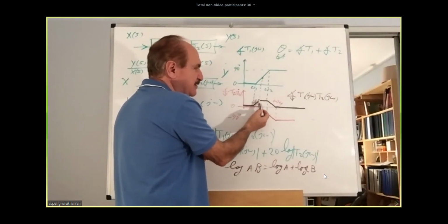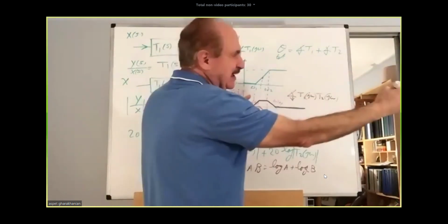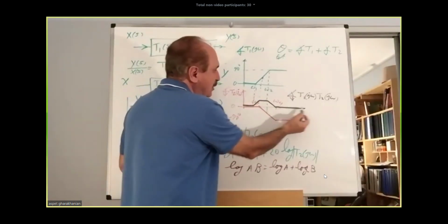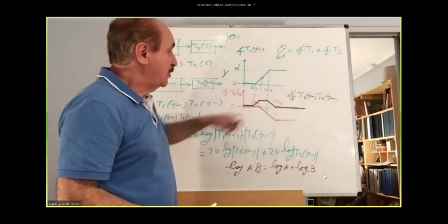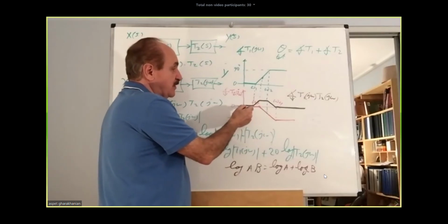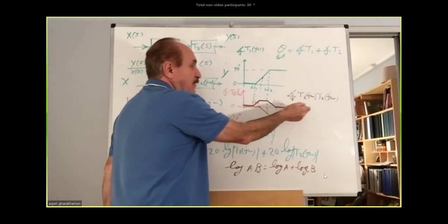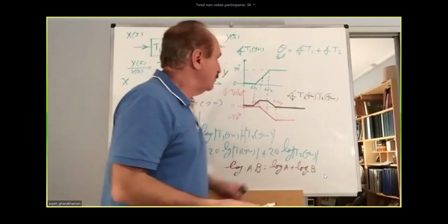It will stay maximally flat, or kind of peak to a maximum, and then it will start going down, and eventually it will become a 0 degrees phase shift. Of course, this combination shows that it must be leading in phase, because the phase angle is positive, and then becoming 0. We can estimate what the maximum will be.